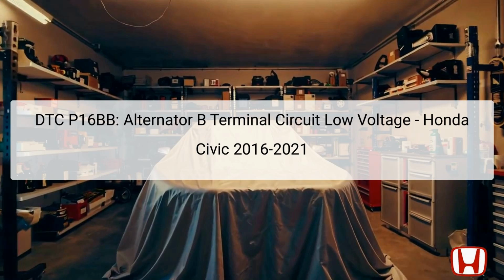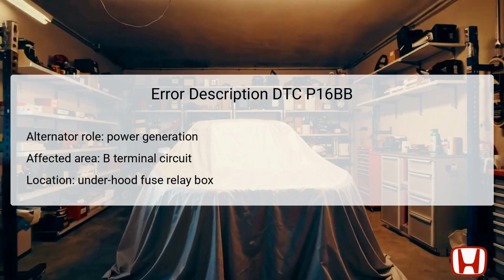The alternator plays a crucial role in charging the battery and powering the vehicle's electrical systems. If this circuit is experiencing low voltage, it can lead to various electrical issues, including battery drainage and malfunctioning components. We will explore the causes, symptoms, and troubleshooting steps associated with this DTC, providing a roadmap for effective diagnostics and repairs. The DTC P16BB specifically relates to low voltage detected in the B-terminal circuit of the alternator.